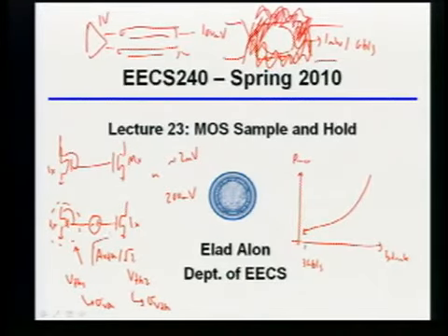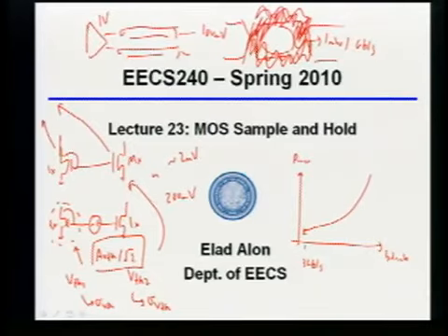So now if you know this, I claim you should know how to answer that first question. Because you can individually take those AVTHs and then do the root sum squares. Or rather I should say, not the AVTHs, but the sigma of the VTHs, you should be able to figure out what that mismatch ends up being. Does that make sense? Or in other words, you can compare both of these to the magic transistor that has no mismatch, subtract their sigmas, and then just be careful that when you do the subtraction, that actually adds the root sum squares. Okay? More questions?